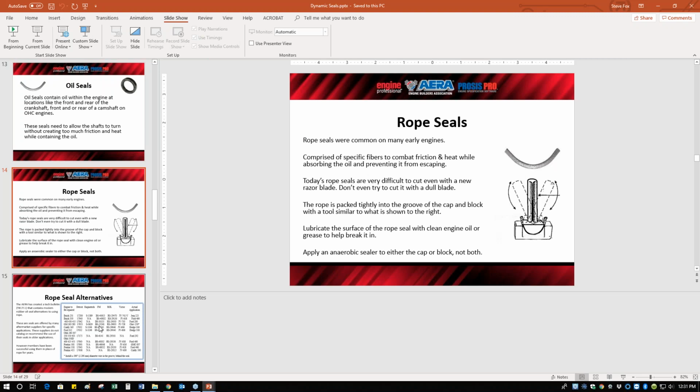If you end up putting it in both, then you can have excess material and it's going to try and extrude out, and then you can end up with potential clearance issues with your bearings. And then excess clearance, now you have oil pressure issues.